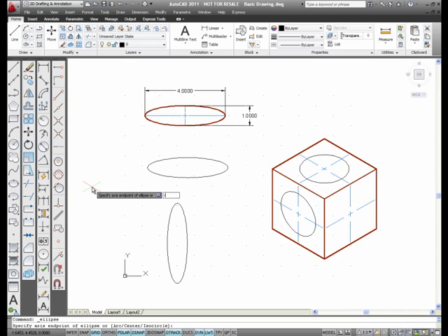I'm going to select the ellipse, I for isocircle, press enter, and pick. This is where you have to make your decision, not after you type in the distance. F5, that is correct. This is correct. It is isoplane right. Type in D for diameter, 2 inches, and that's it.